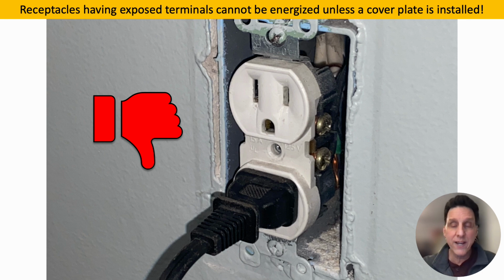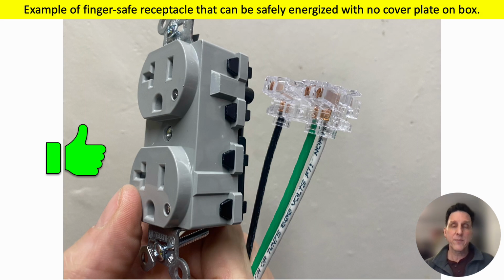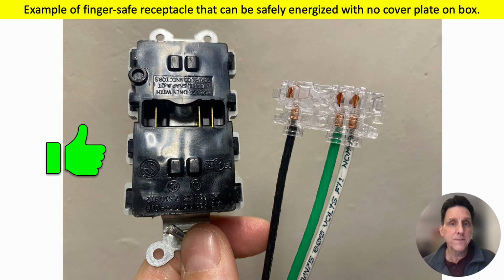All right, now let's take a look at a finger-safe device. Receptacles like this and other types of finger-safe devices, there's different types. This is just one example. There's no exposed terminals, so you can't really get a shock. Right? You're not going to accidentally touch any exposed live terminals because there aren't any. So you can install receptacles like this in the wall, in the box, right? Energize these. You don't have to put the cover plate on because you can't really get a shock. There's the back of that receptacle. And again, a device like this, whether it's a receptacle or even a switch like this, you can energize the wires. You don't have to put the cover plates on, right?